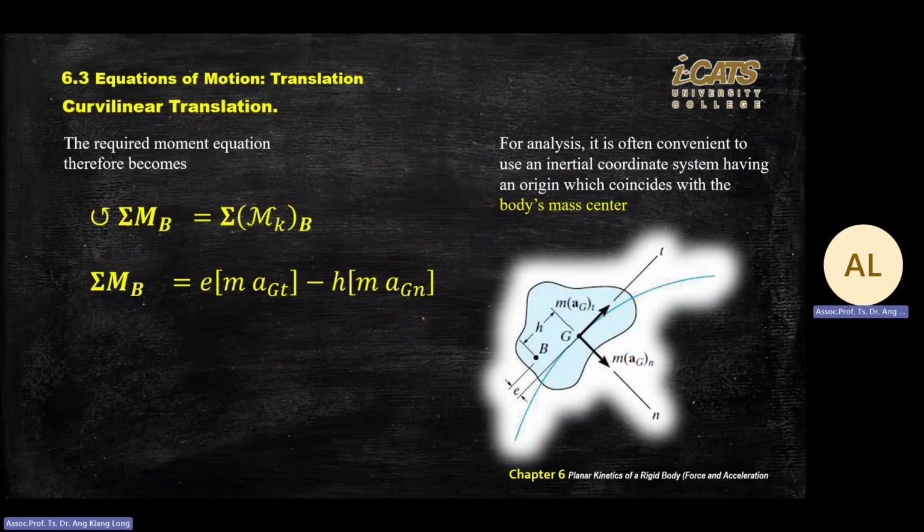Because you're going into your year 2 next semester, this should not be repeated. Careless mistakes here should not be repeated in your year 2. So I highlight, starting from your test 2 and final exam, your W always points to the center of mass, and do not put it in another place. And also, every time you have a contact point, you automatically have a normal force there, always perpendicular to the object, always pointing to the object to support.